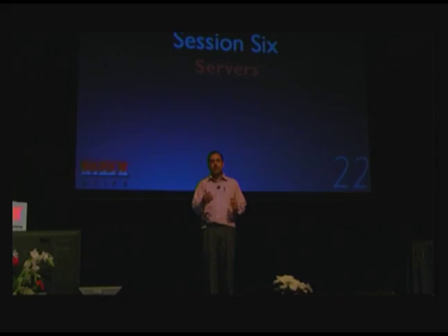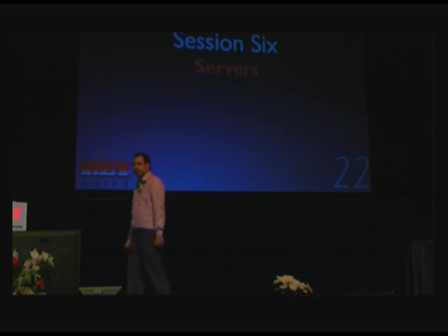The directory cache was, frankly, based on an observation that we noticed pretty late in the game. Like I described, it's specifically targeted at the category of workloads that use the non-temporal flow, and that specific inefficiency wasn't noticed until late in the game for Nehalem-EX to respond. So we went ahead and put it in.